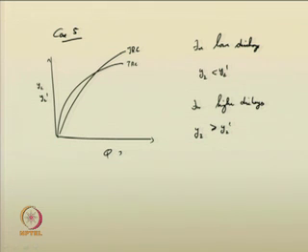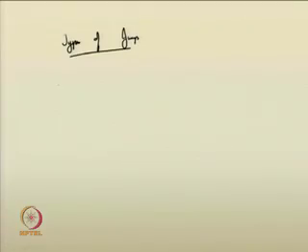Okay. So, by providing proper stilling pools in these cases, you can have higher tailwater depth also for lower discharges, and that can ensure better jumps. Fine. Now, for designing the stilling basins, you need to suggest the types of jumps, whether it is undular, weak, oscillatory, steady or strong, whichever type of jump is there, that you need to provide beforehand itself.